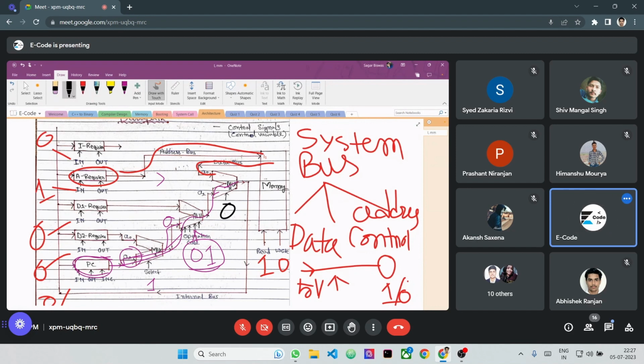If we send 0 in this multiplexer, it will directly pass this input and cut the other input. Then we get the instruction, and we have to store this instruction in the instruction register. So we have to give a 0 signal to this input and a 0 on signal to this input, so that this instruction can be copied to this register. So this is how these things basically work.